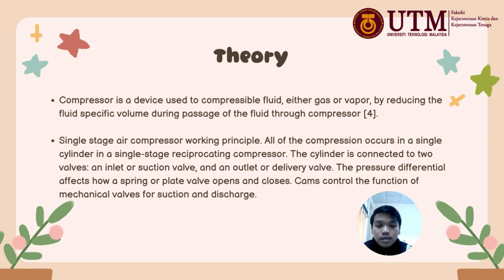The cylinder is connected to two valves. It has an inlet, or we call it the suction valve, and an outlet, or we call it the delivery valve. The pressure differential affects how a spring or plate valve opens and closes. Cams control the function of mechanical valves for suction and discharge.